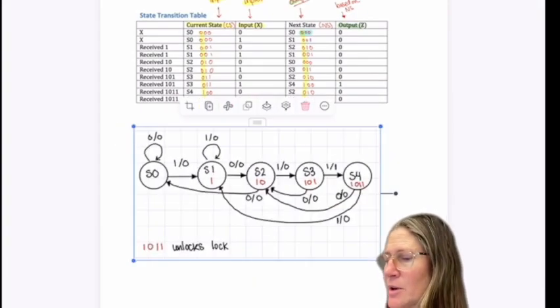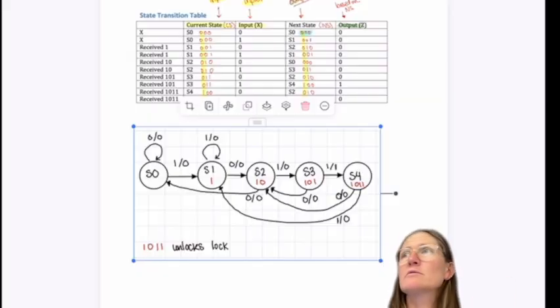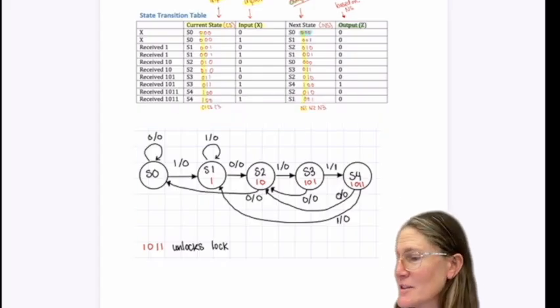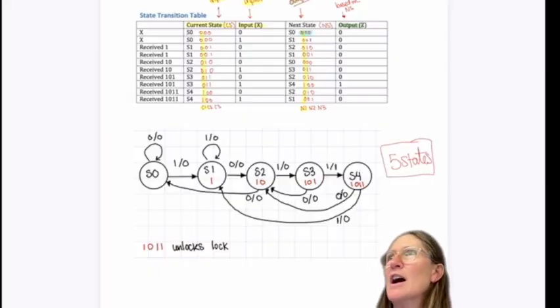First off, how many states does this system have? So we have 0, 1, 2, 3, and 4. So it has how many states? 5 states. How do I write 5? The decimal number 5 in binary is 1, 0, 1, right? So how many flip-flops am I going to need for this? 3. Okay.